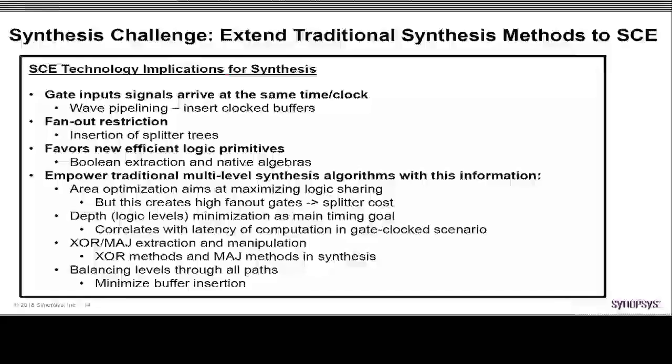Okay, synthesis. Synthesis here, we have a big challenge because of many factors. Fan out is equal to 1, as I mentioned, so you need splitters. Also, in CMOS, you're looking for levels. So if you have a 2-input NAND gate, if input A is sitting at 1, you can wait for infinity for input B to reach the level 1, and the output is 1. Here, you're talking a pulse of about less than a picosecond with a height of 2.07 millivolts.